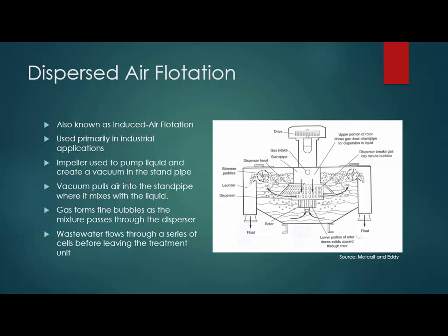The next type of flotation that the book discussed was dispersed air flotation. It's also known as induced air flotation. Now in this case, it's primarily used in industrial applications, but in this setup there's an impeller which is used to pump the liquid, and when it pumps the liquid, it actually creates a vacuum up in the standpipe, which pulls in gas.